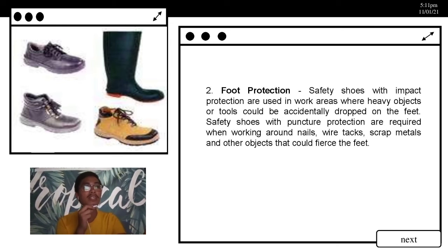The next one is the red rectangle with the white C letter, which indicates electrically conductive footwear. These are for industrial work environments where low power electrical charges can create a hazard for workers or equipment. The warning here is that this footwear should not be used where contact with live electrical conductors can occur.